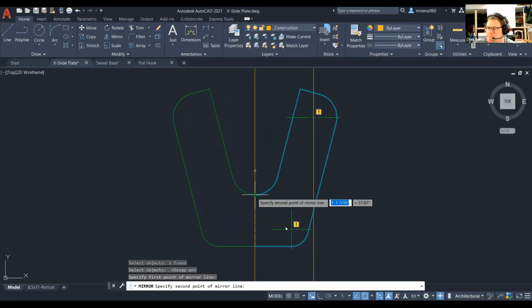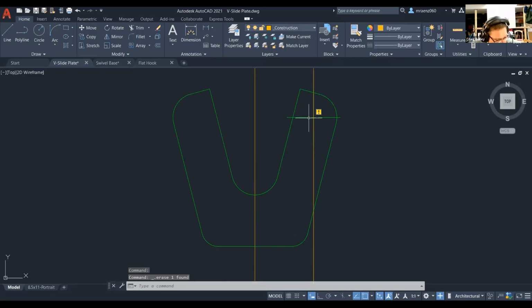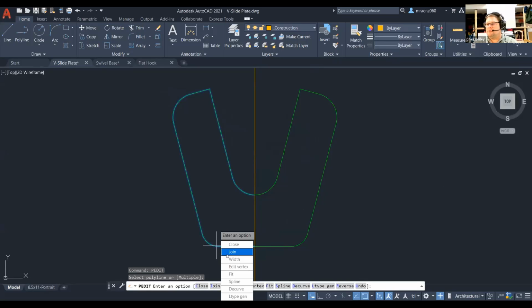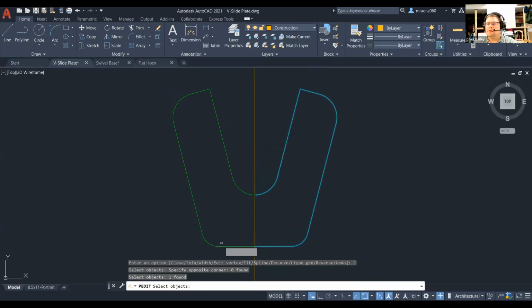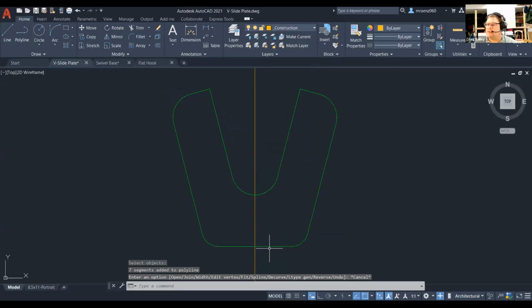Yes. That's it. Erase source? No. Okay. Awesome. Now, I'm going to harp on everyone on this one. Michelle, please connect those two polylines so that you have one big polyline. And I'm going to start harping because in order to extrude things and get into the three-dimensional approach of AutoCAD, you don't ever want to have separate line segments or arc segments.